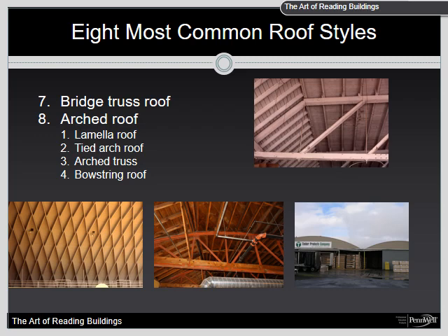The design for this popular type of roof was first used for arched bridges and then made its way into buildings by the thousands from the 1800s to the mid-1900s on both small and large commercial type structures. Although the original bowstring bridge was all metal, bowstrings used for roof construction can be all iron, all wood, wood and iron, and in later years all steel.